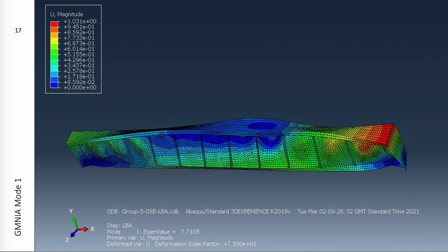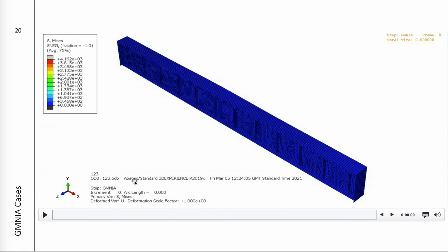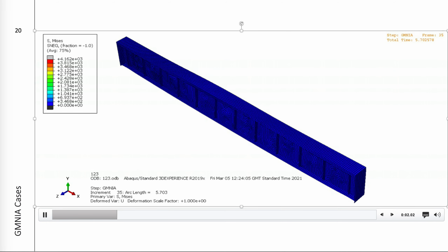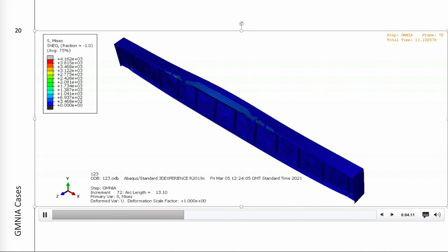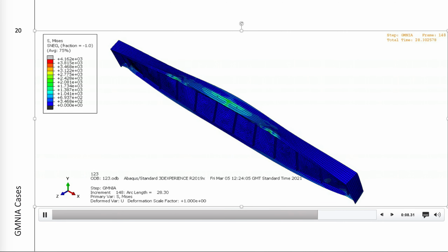It was found that the most critical case was a combination of modes 1 and 2 with excess deformations at the ends with high stress concentrations on the top flange, 1 being LTB, 2 being distortional buckling. This combination of modes was chosen because of the similarity in deformations. These failure modes 1 and 2 dominate, and adding additional failure modes such as 3 and 4 does not decrease the load capacity.